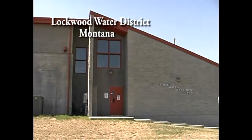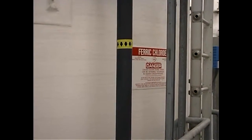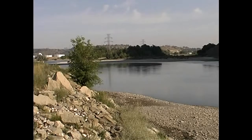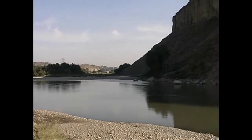With the revised arsenic MCL looming in the future, the City of Billings began experimenting with coagulants other than alum to increase arsenic removal. Billings converted to ferric chloride as a coagulant. Arsenic in the Yellowstone River, because it's a surface water source, is arsenic-5. Arsenic-5 is relatively easy to remove.